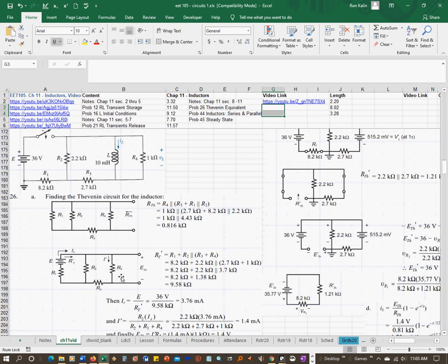So what you do here is R3 and R4 are in series because this is open. Okay, you really need to look at this part of it. This is an open circuit. So you're wanting the voltage across R4 is what you want here. So you calculate RT, which ends up equaling 3 and 4 are in series, and then those two are in parallel with R2, and that's in series with R1. So they did that math, and you end up with 9.58 kiloohms.